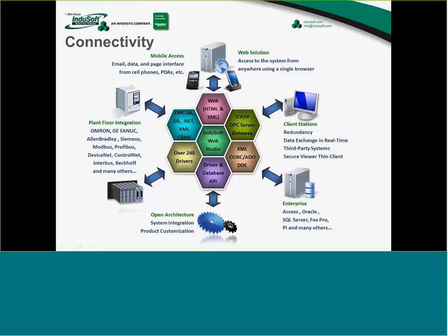But it's not going to be uncommon for you, and many of you will have this circumstance where maybe over time you've had one brand of PLC network in the plant, and you also have to communicate to another brand. And how do you do that? Well, if your license supports multiple PLCs, like one of our 1500 tag licenses supports 3 PLC networks, so you could communicate to an Omron, a Beckhoff, and an Allen Bradley simultaneously. And then real neat is notice that these arrows are all bidirectional. You could also then share information between those dissimilar PLC brands that might not have been able to talk to each other through the tag database.